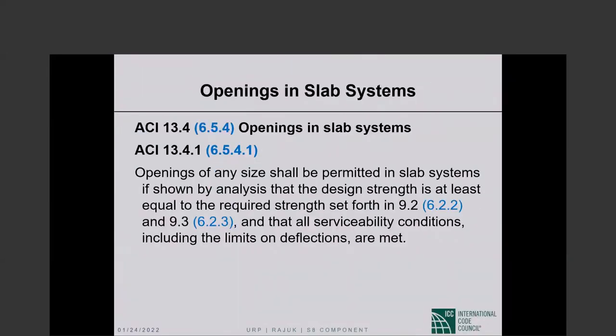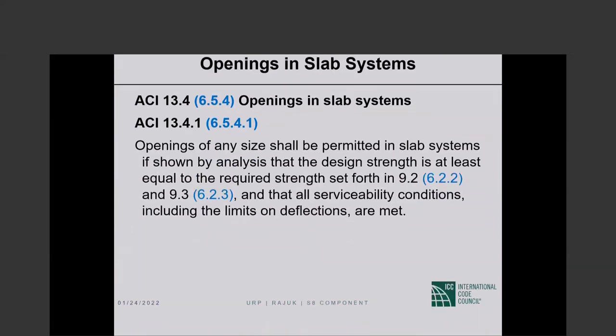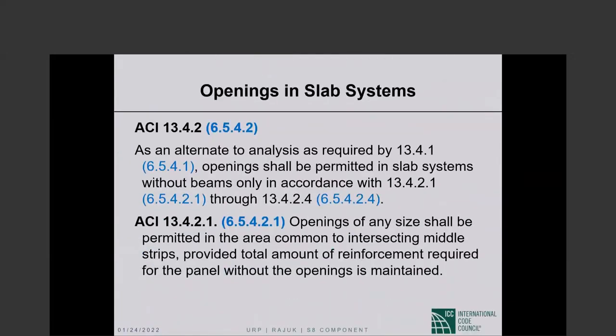Openings in slab. Openings of any size shall be permitted if shown by analysis that the design strength is at least equal to required strength and that serviceability conditions are met. Now, as an alternative to that kind of analysis, these are simple rules that you can follow.